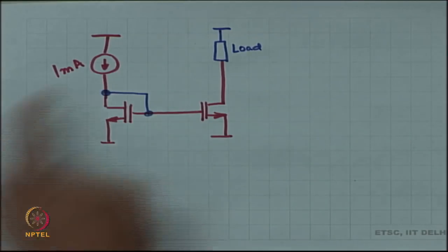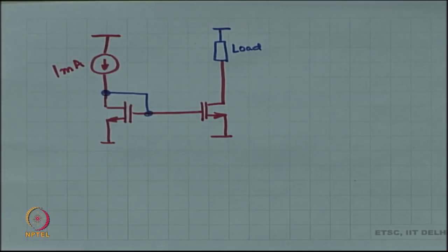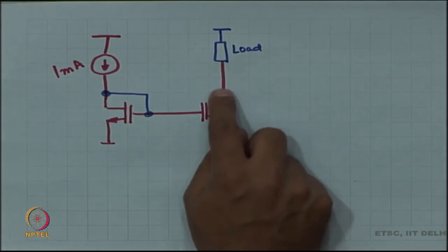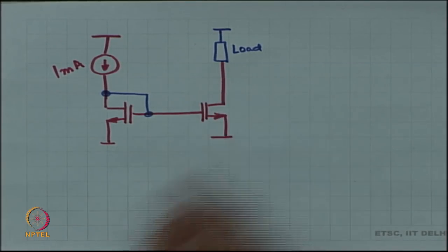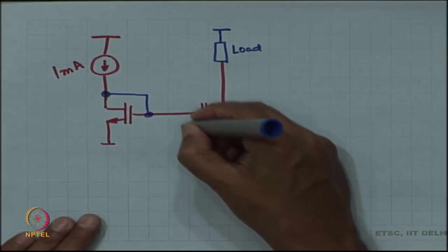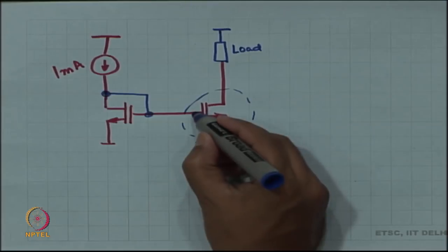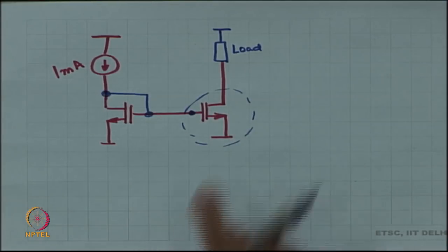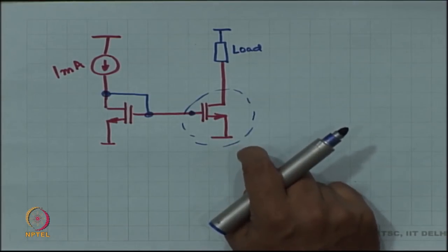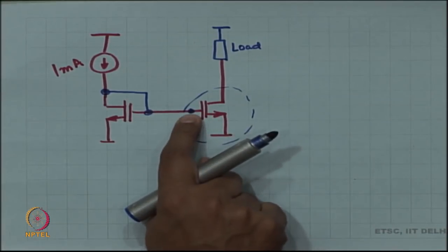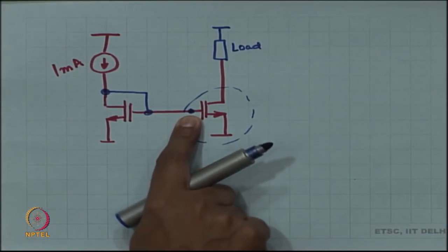Okay. So, somebody has given me this 1 milliampere and I have to create another 1 milliampere. So, the MOSFET itself is the current source. So, this is the source, and I have to decide what is the right gate voltage. Remember, this current source is a controlled current source, it is a voltage controlled current source controlled by the voltage at the gate.